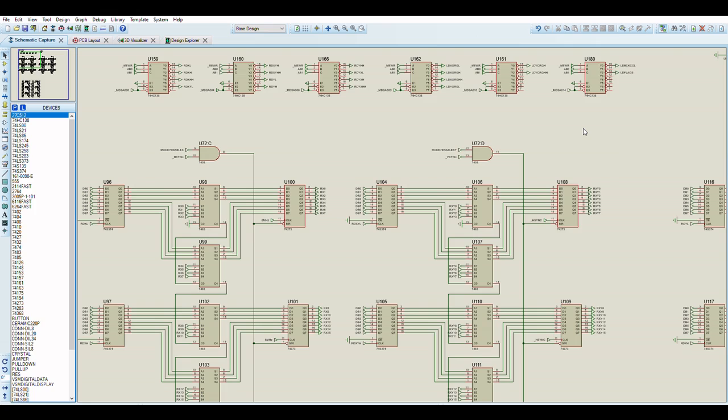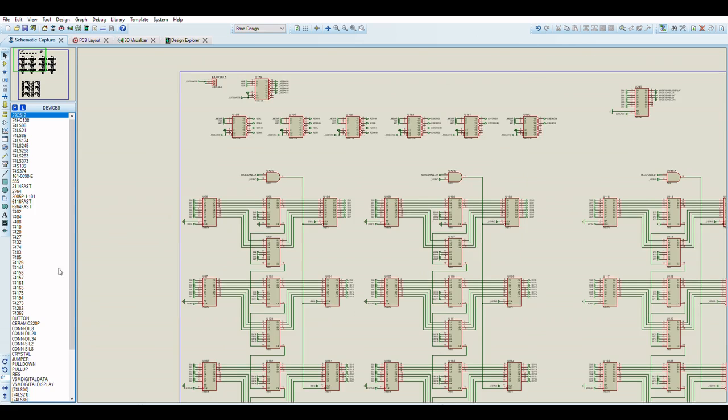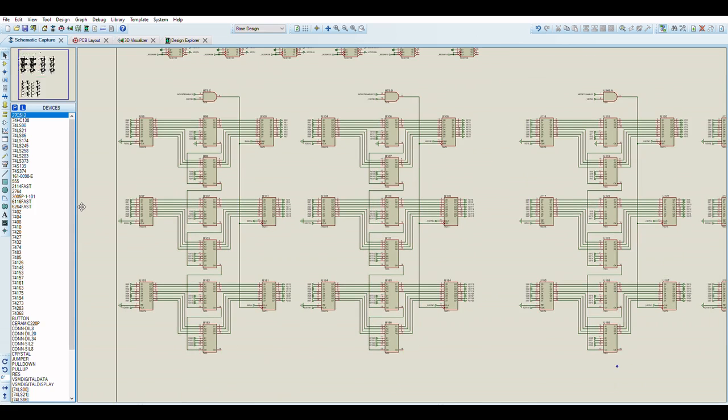This has the notion of internal registers, which every horizontal pixel and every vertical scan line will accumulate values for each clock. What this means is that you can have a horizontal pixel position with 24 bits of precision accumulating another 24-bit value.